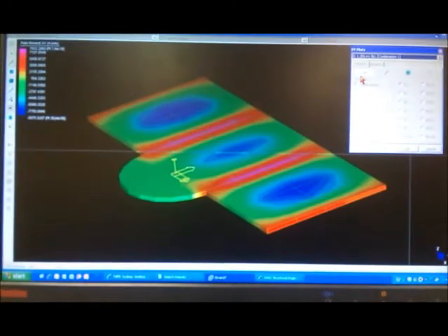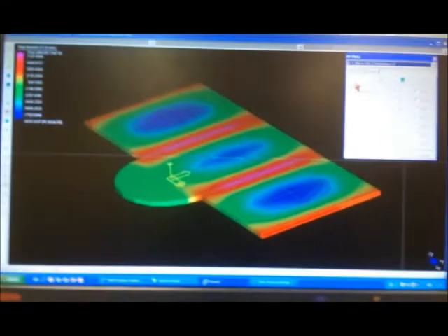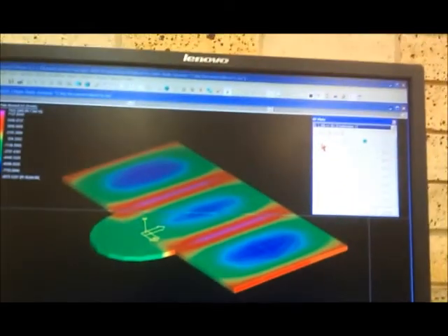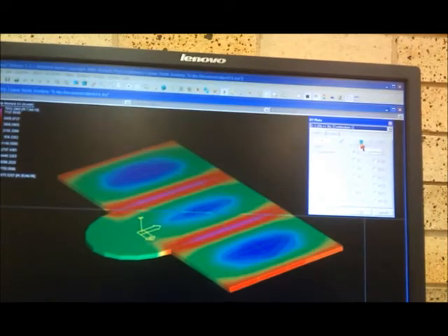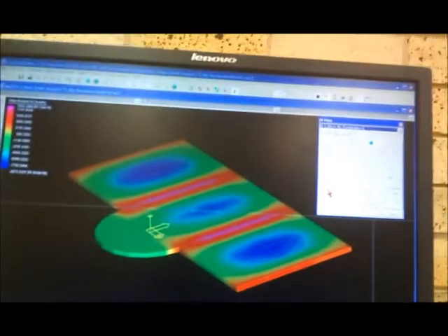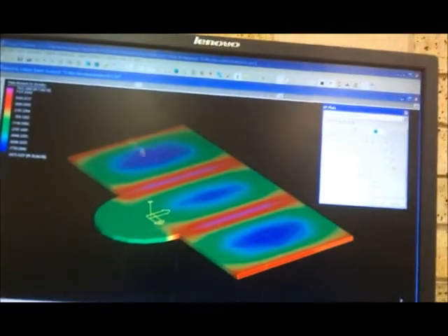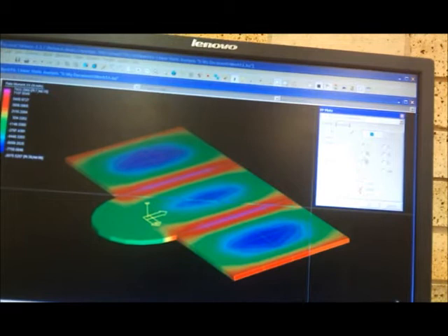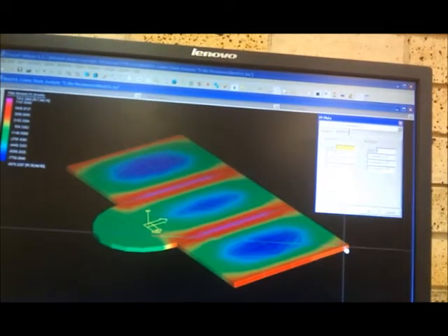Quantity. I'm drawing a graph with the bending moment, which is the bending moment of the plate. So I should have the plate selected. So I'll select plates from here. And I'll select moment from here, and I'll select global to be same as this one, XX. Right? And I'll say position.